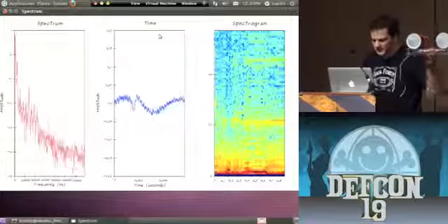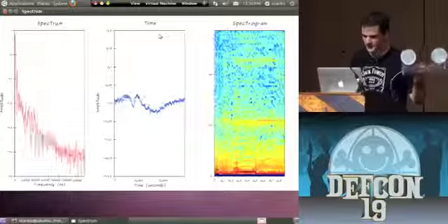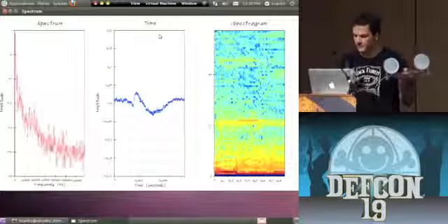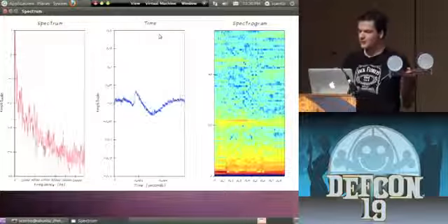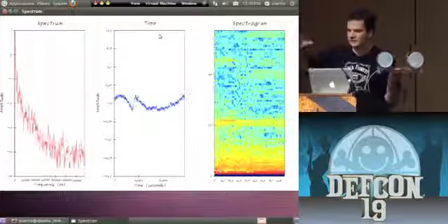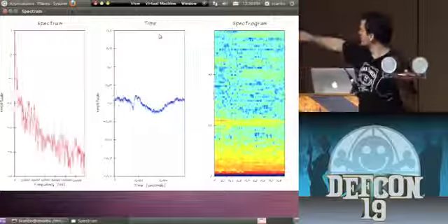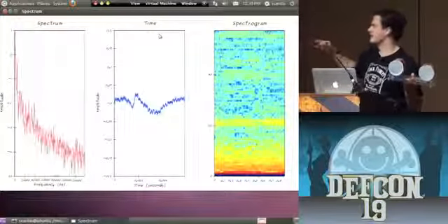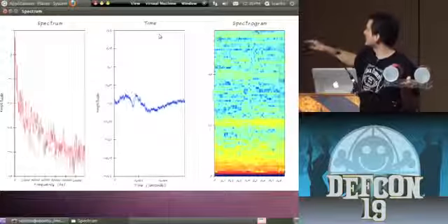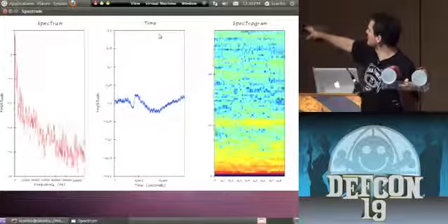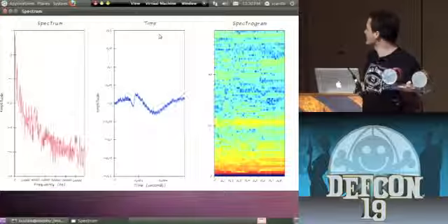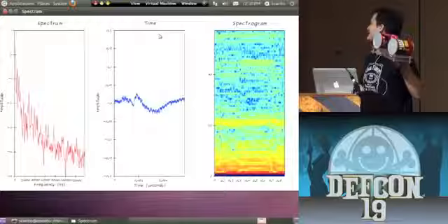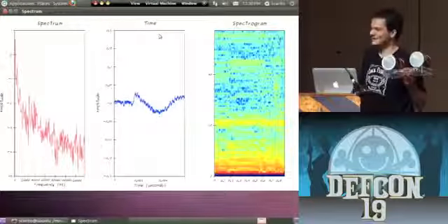And the other thing, which I haven't actually seen yet, which I'm a little surprised by, is that this thing operates in the Wi-Fi band. And there's a lot of noise. I'm not exactly sure why that's happening. That wasn't happening before. But what you do see occasionally is these pulses towards the top end of that. That's actually Wi-Fi signal bursts from the thing transmitting. I think it's a 20 megahertz wide signal. What you see for that is a little pulse in the middle of the time window. Unfortunately, no one's using Wi-Fi devices in here because I'm not picking anything up. So I guess everyone's being smart now and they're not using Wi-Fi at DEFCON.